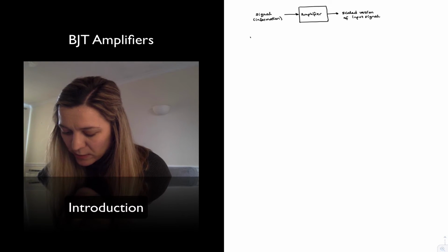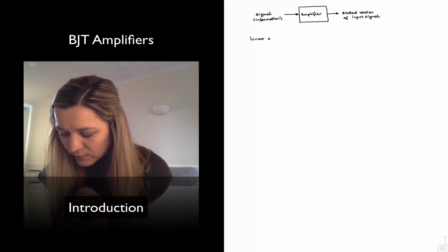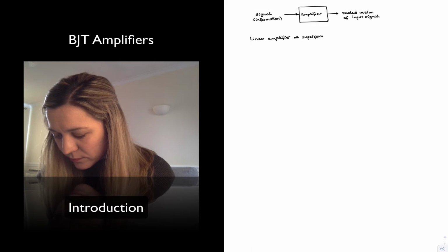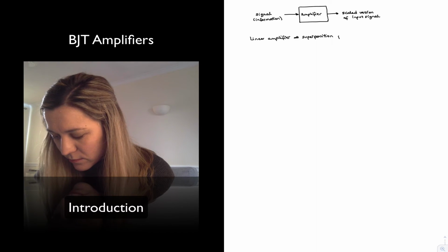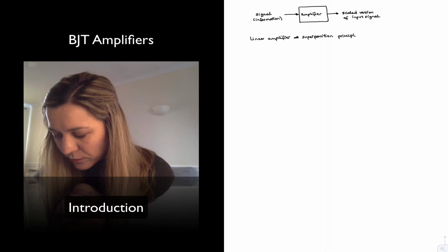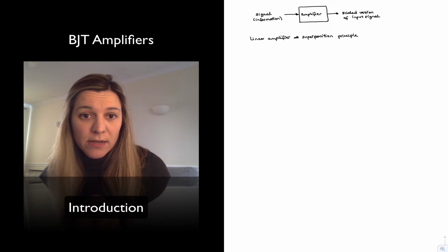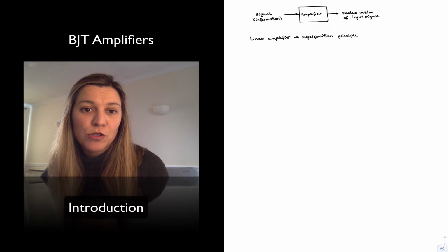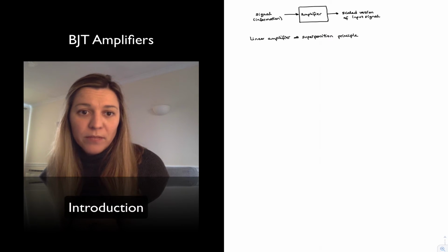So for a linear amplifier, we can apply the superposition principle, which basically says that the overall output of the circuit or of the system is equal to the superposition, or the sum, of the individual outputs to the different input stimuli.